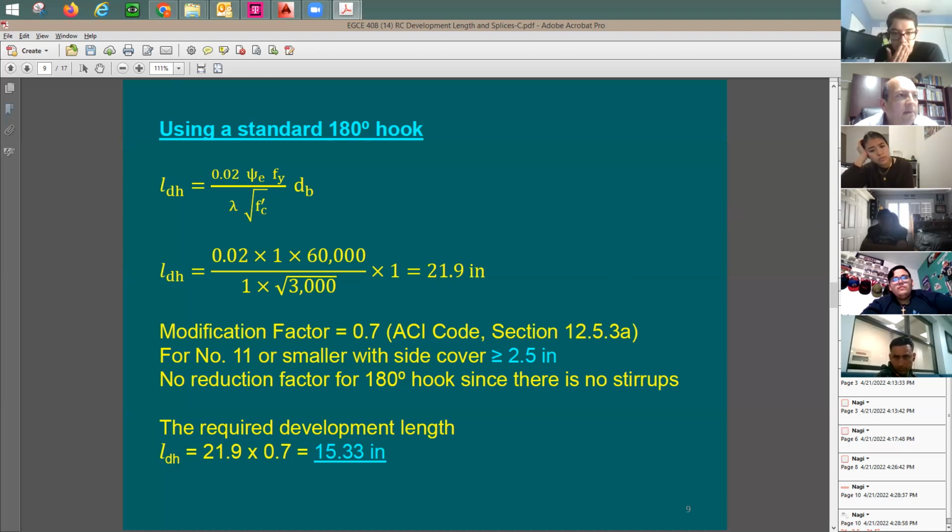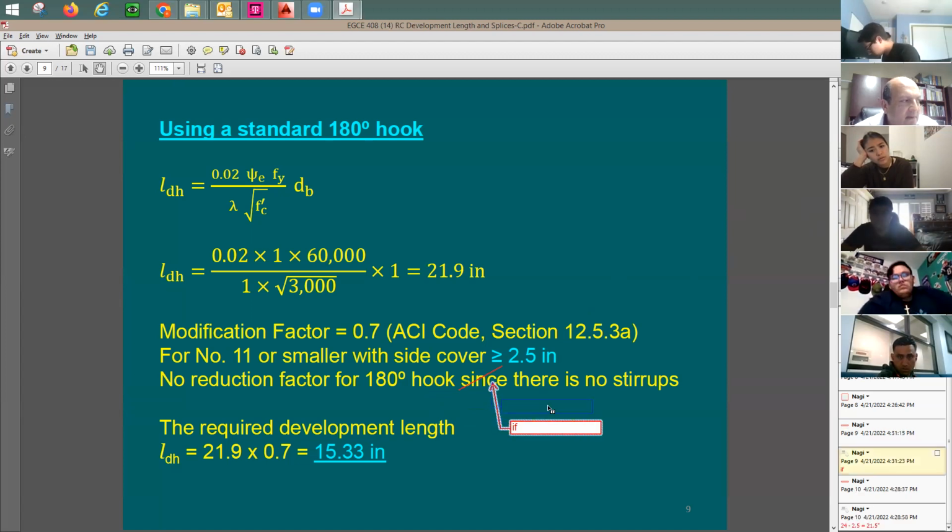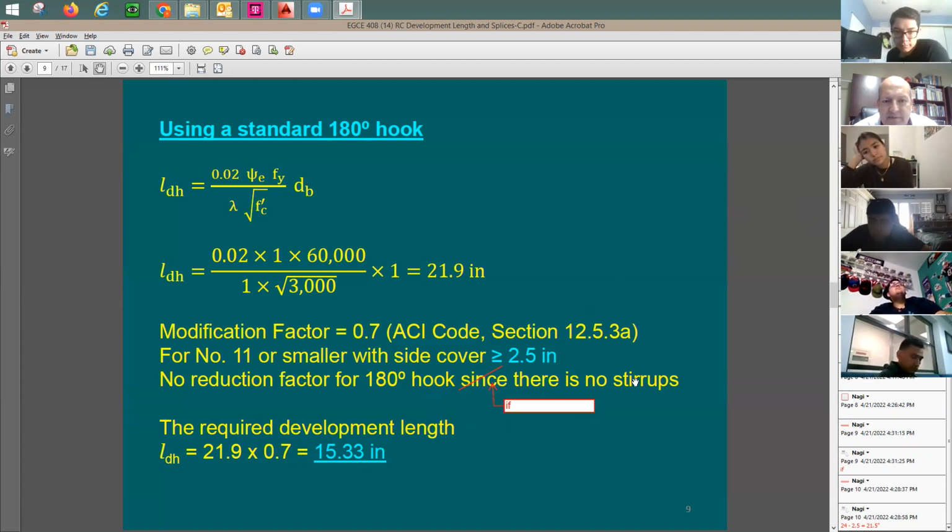Okay. And then maybe I just didn't understand, but like, why can't you just shift the hook to the right? Like, is there a right limit to the hook as well? Does this make sense now? Once you see here, you feel that, oh, in this problem, there is no stirrups or ties, correct? It should have been, if there is no ties, stirrups or ties. But in our case, we have ties. So I should be able to use this reduction factor. I see. Now, your second question. No, the wording, you're right. I mean, this should have been there.